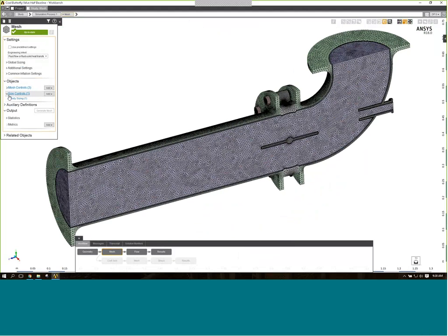All I've done is turn on curvature and proximity global sizing function, and then I applied a body sizing to the fluid domain. And also another thing I want to point out is meshing in AIM is physics sensitive. So you'll notice under the engineering intent, it knows that this mesh is intended for fluid flow or conjugate heat transfer simulation. So it automatically adjusts the default settings to give you a mesh that is already highly optimized for this application.